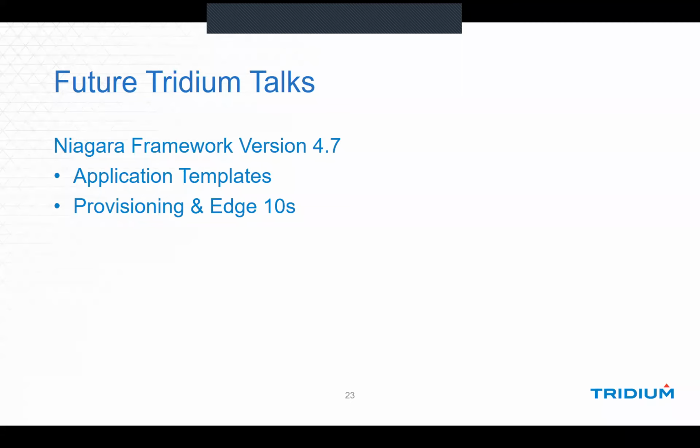I can't see the gentleman's name, but it says, can we also do alarms and history extensions configured using bulk deploy? Answer is yes. The way the Niagara templates work, you put your extensions and everything into the space that you're working on before you make the template. And so anything that was in that template, when you make it, it's going to pick it up.